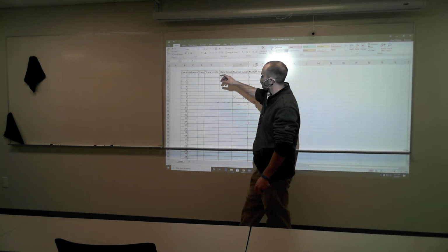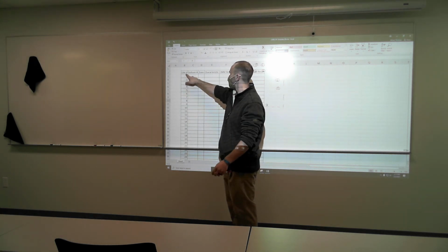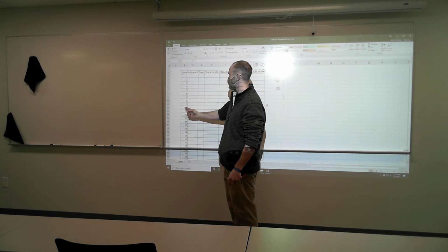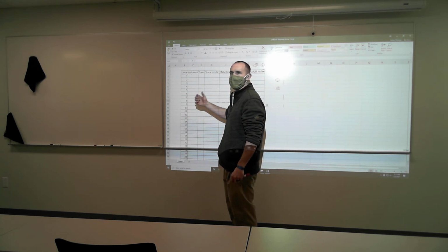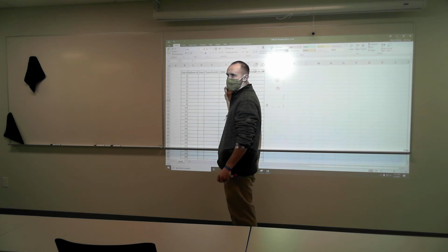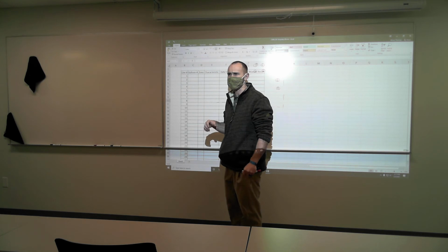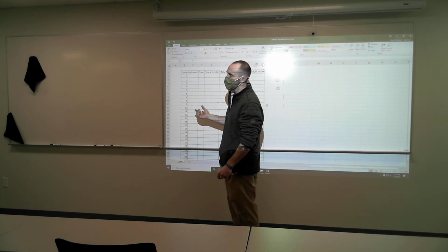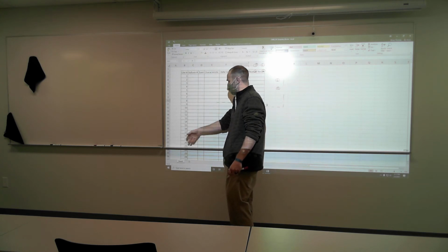So this is just a grid where we're going to systematically verify that we checked everything. So we have line number. This is so that I can tell you, hey everyone, look at line number 10. And the line number may not necessarily correlate with the balloon number, as you'll see. Why would it not correlate? Well, maybe we're using two different gauges to check the same thing. Why would we do that? Well, maybe the gauge itself is not so reliable. So the line number is just part of the sheet format.